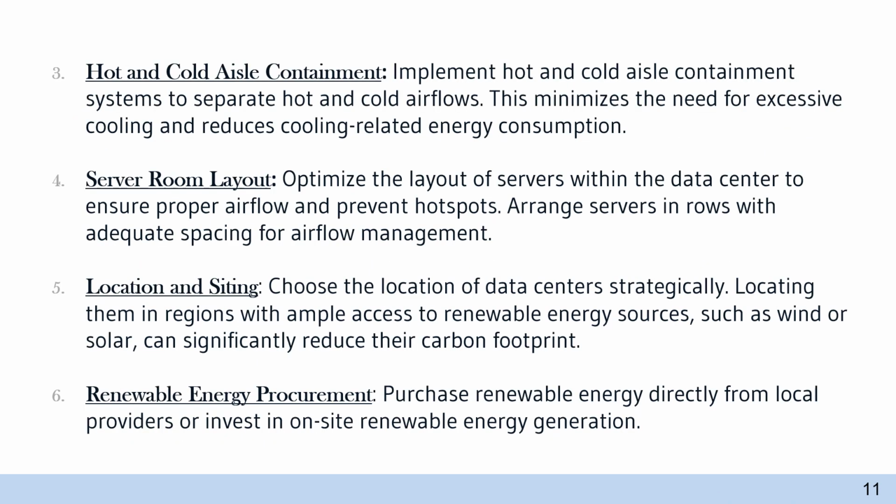Next is hot and cold aisle containment. Implement hot and cold aisle containment systems to separate hot and cold airflows. This minimizes the need for excessive cooling and reduces cooling related energy consumption. Next is server room layout.